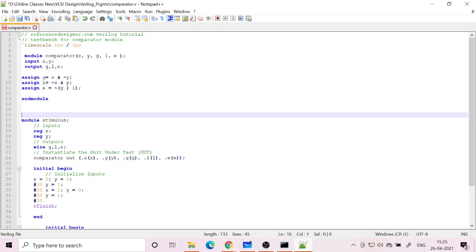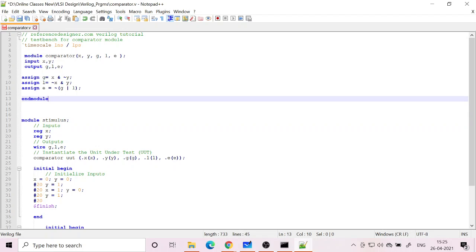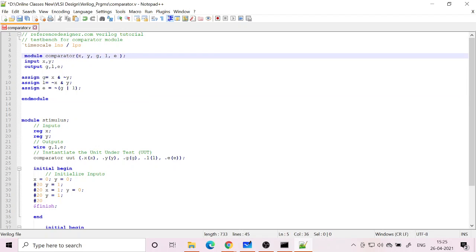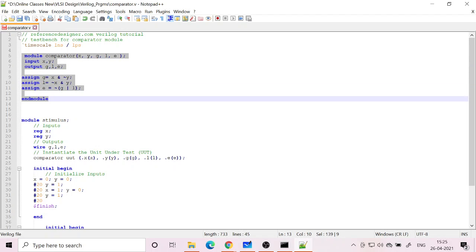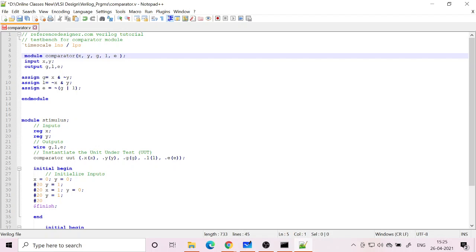Similarly, there is some preference. So if you want to take the OR operation first, you put the bracket there, and that's it. You end the block with the keyword endmodule, which doesn't have any semicolon at the end, but all other statements have a semicolon at the end. So this is all it takes to describe our hardware, which I have drawn earlier.